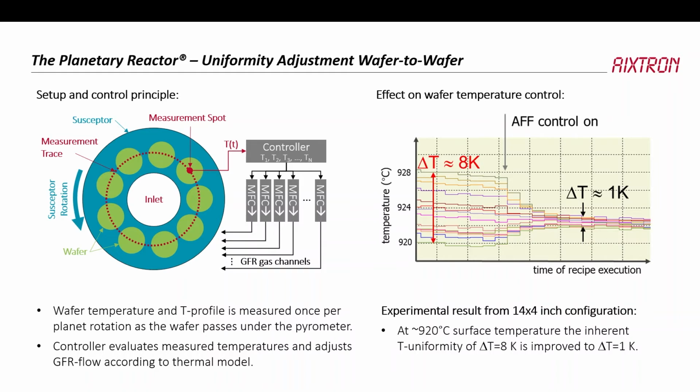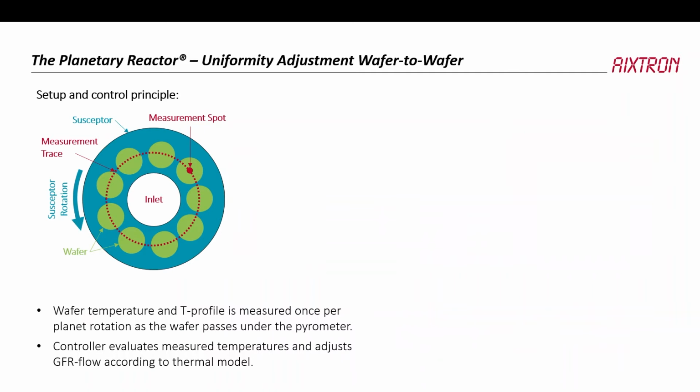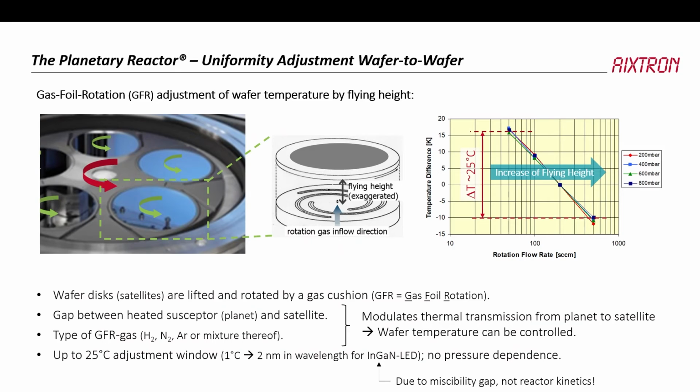There are some other tricks that I didn't bring here to this conference or to this meeting, which is you can also have a split inner and outer gas foil. You have a gas foil in the center, you have gas foil at the outer edge. And so the number of MFCs and so forth doubles by this, obviously, but now you can actually introduce different gases, like hydrogen. Hydrogen has a much better thermal conductivity than nitrogen does. And like this, we can also change the profile.